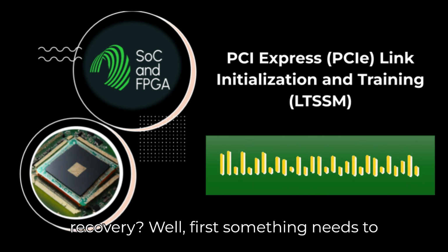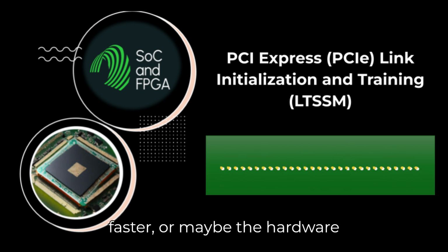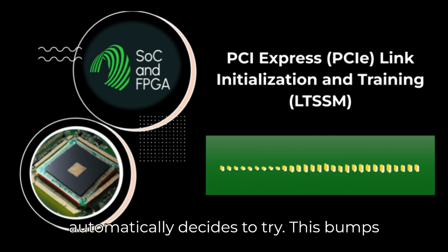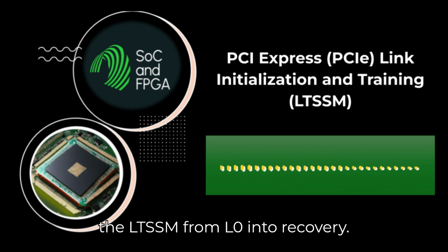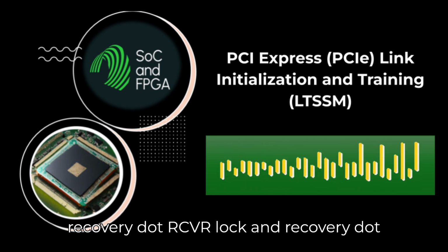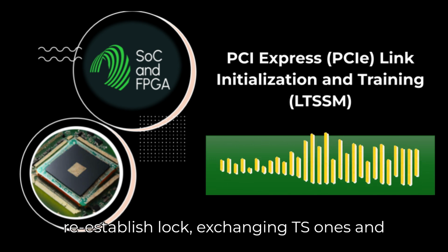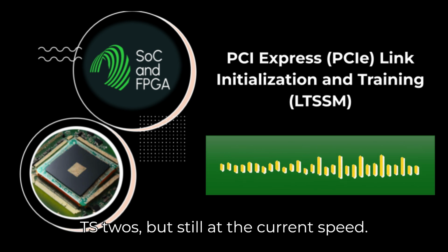Well, first, something needs to trigger it. It could be software saying go faster, or maybe the hardware automatically decides to try. This bumps the LTSSM from L0 into Recovery. Inside Recovery, you have substates like Recovery.RcvrLock and Recovery.RcvrCfg. The first goal is just to reestablish lock, exchanging TS1s and TS2s, but still at the current speed.